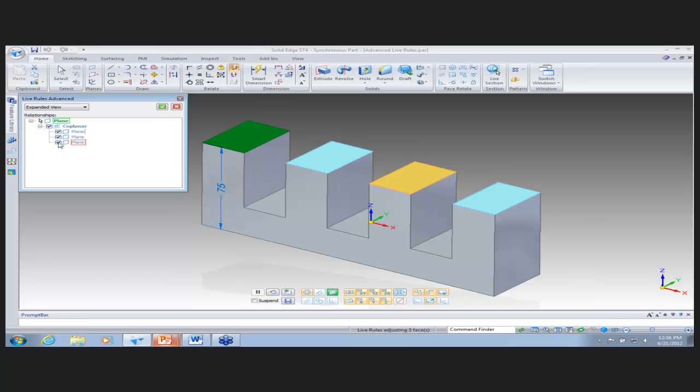Within the dialog box here, you can right click and there are some shortcut menus. If you click on the coplanar move or each of the faces, it gives you different options. There's a relationship shortcut menu when you right click a relationship heading entry, and an element shortcut menu is available when you right click an element entry on the advanced page, such as a face or reference plane, one of these planes here. When you click on the element shortcut menu, you have the options to perform a variety of tasks. You can add the related element to the current select set. You can search the model for additional elements based on geometric condition. And you can also save these faces for other moves as well.